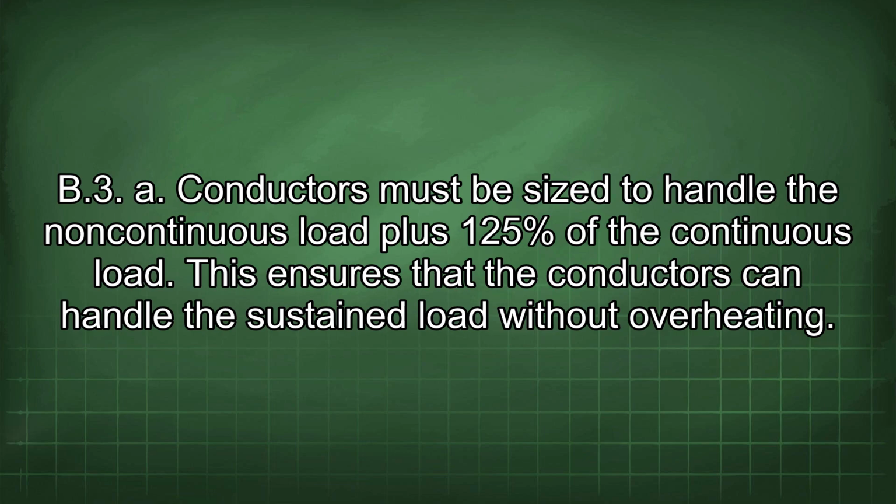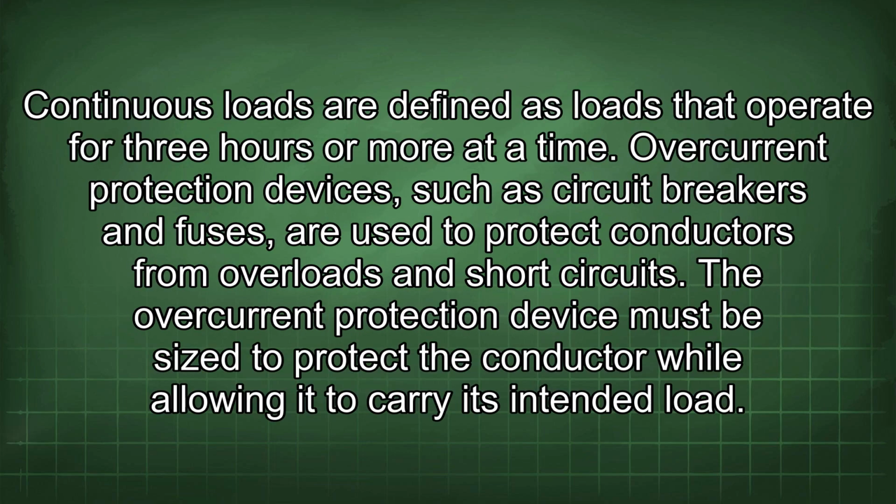Conductors must be sized to handle the non-continuous load plus 125% of the continuous load. This ensures that the conductors can handle the sustained load without overheating. Continuous loads are defined as loads that operate for 3 hours or more at a time.